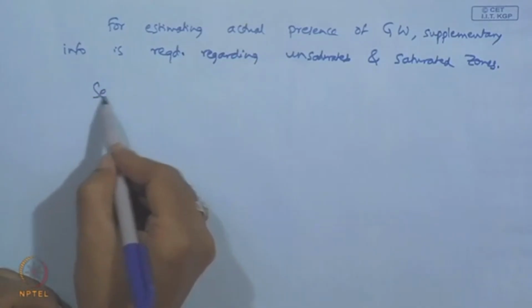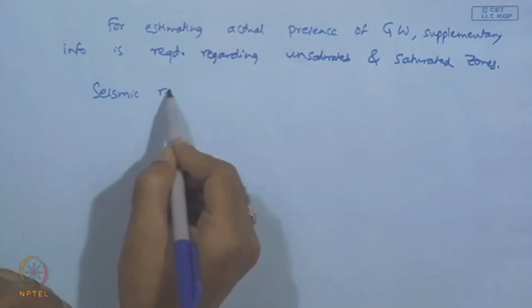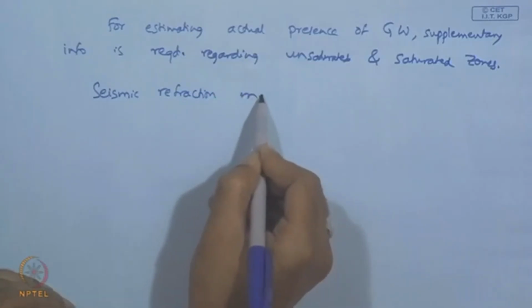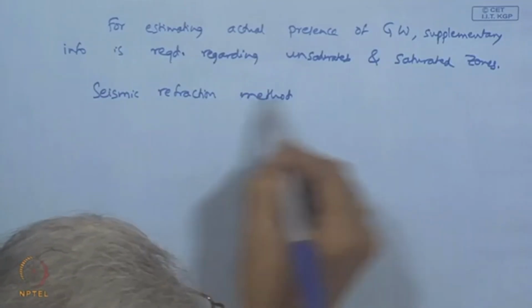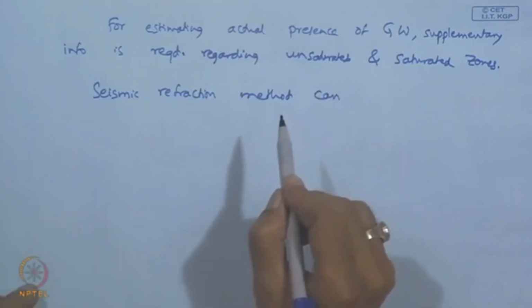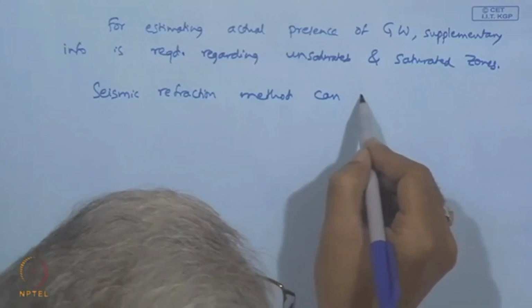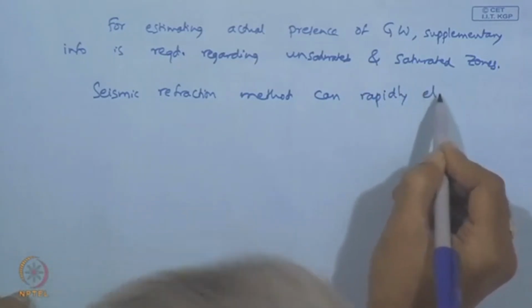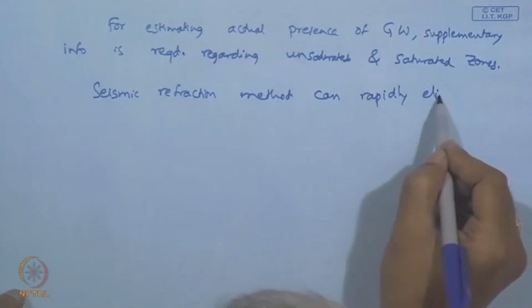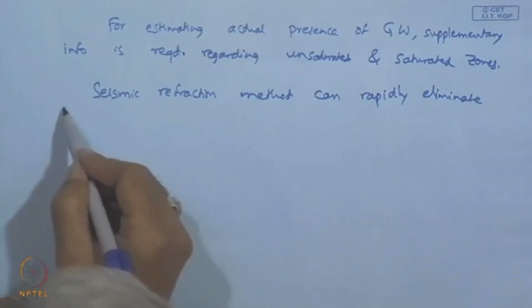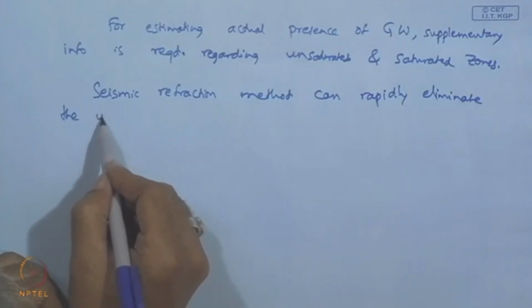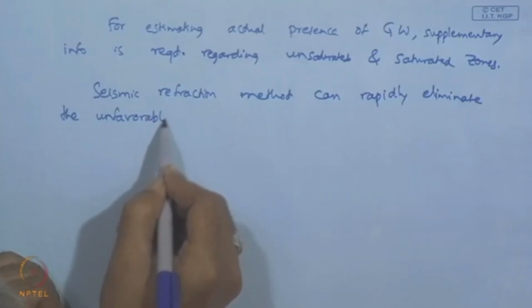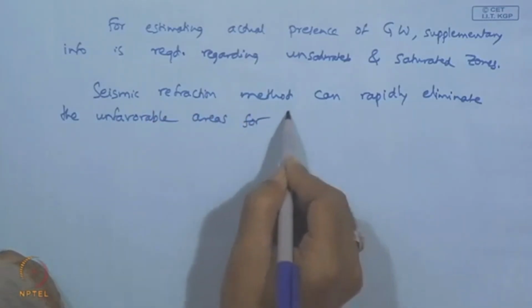So, this seismic refraction method, when applied, can rapidly eliminate the unfavorable areas for test drilling.